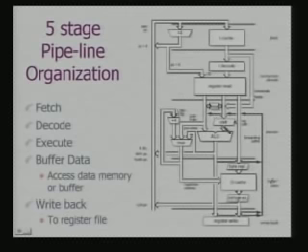This is the same barrel register, that shift operation that I talked about. There will be a multiplier block, and these are all operations to do with address manipulations. So pre-indexing and other things, if it is to be done, then this multiplexer comes into play, this operation takes place and it goes back.